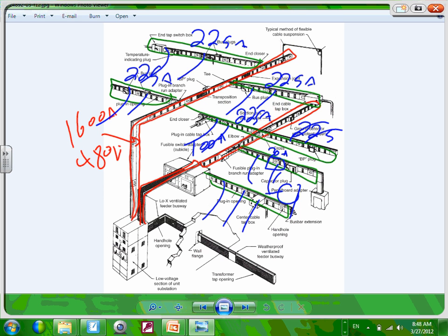I assume it's considerably more expensive than conduit. Absolutely. 4 times, 10 times. I like percentages. You can hold me accountable on that. I don't think it's 4 times though. I would say probably from 50% more to twice, 100% more. So if the system is to cost you, say, $100,000 to do it with conduit, it might cost you $150,000 to do it with busways.